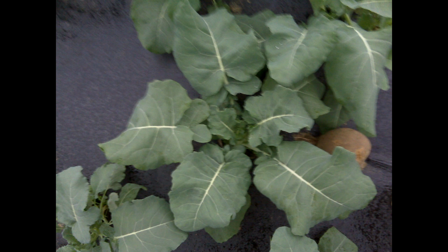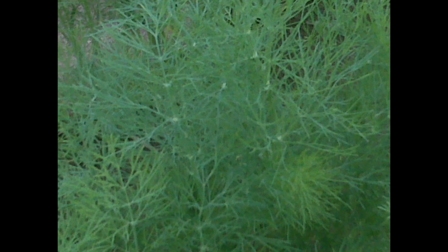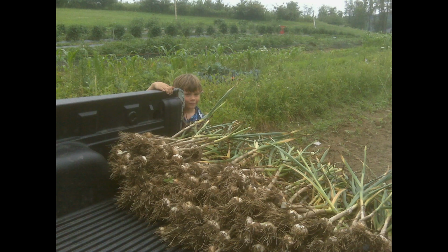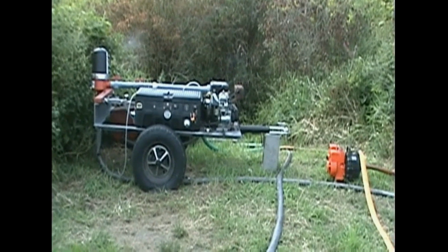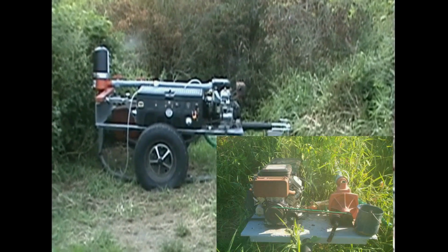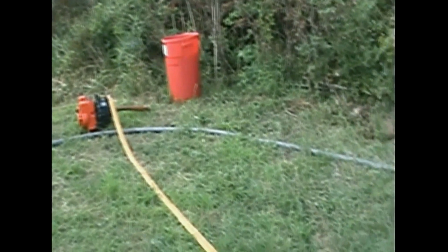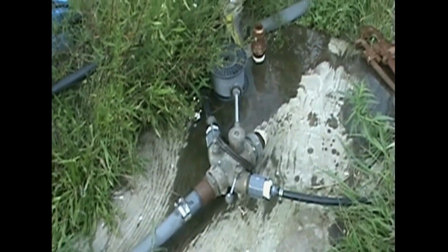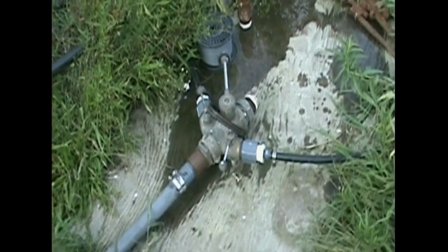I don't think you see it in this video, but there was a massive irrigation system. It's a 2-inch pump that I built with an 18 horsepower Briggs & Stratton twin cylinder engine. Again, fully automated, pressure cutouts for burst pipes, all kinds of crap. I went to the max. So this is both our main and secondary irrigation pumps. They feed off to the valve system, which controls distribution of water to any selection or combination of micro sprinklers, drip irrigation, and big overheads.